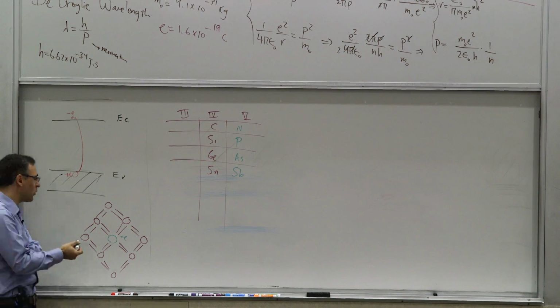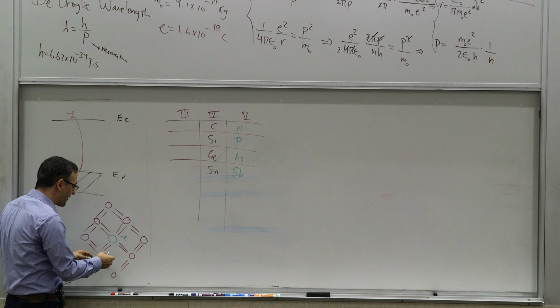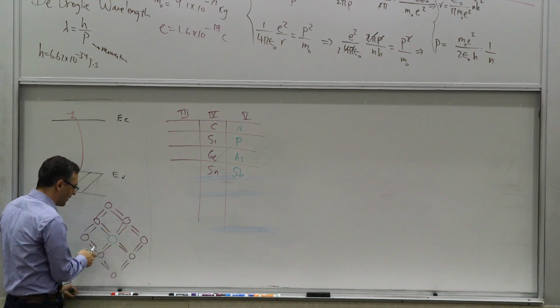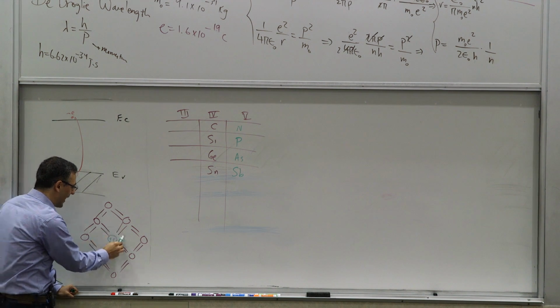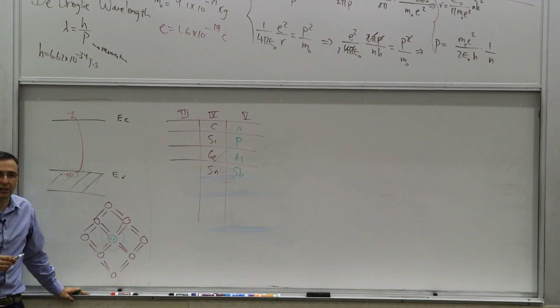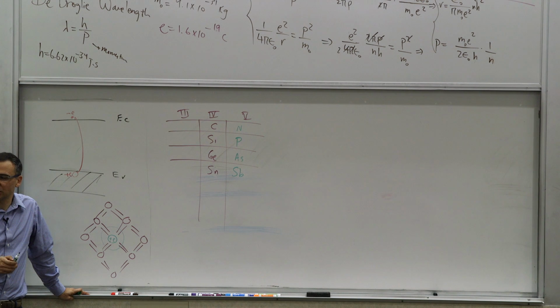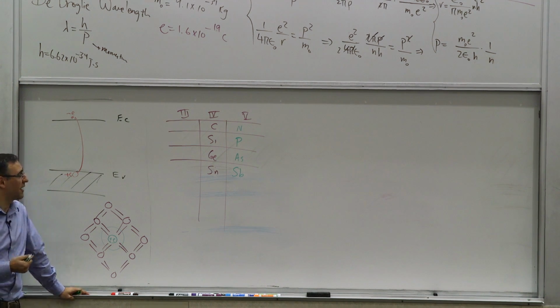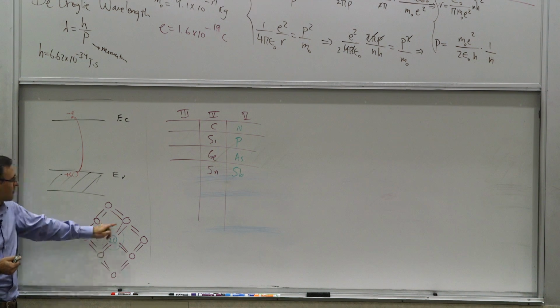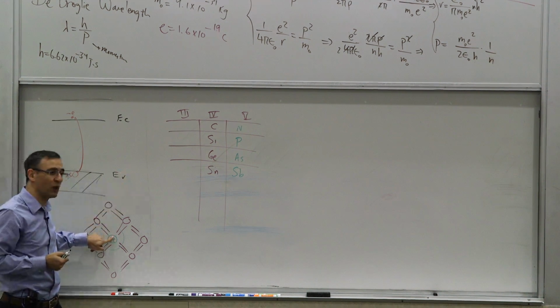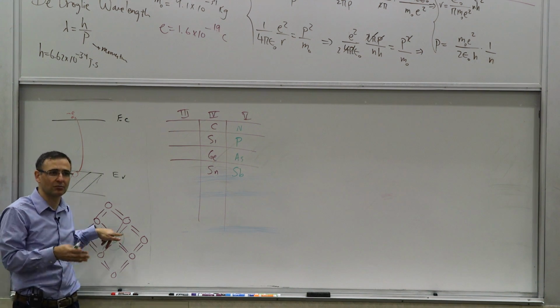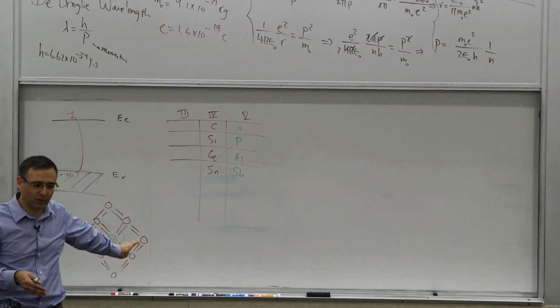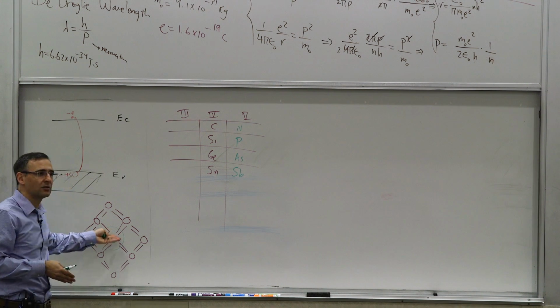Now, we can actually see this quantitatively, because if you think about it, if you take away this electron, this area will have a net positive charge. This would be a positive ion, because the only difference between, let's say, phosphorus and silicon, or arsenic and silicon, is that phosphorus has 1 extra proton and possibly a couple of extra neutrons, which are not important in this discussion, in its nucleus, right?